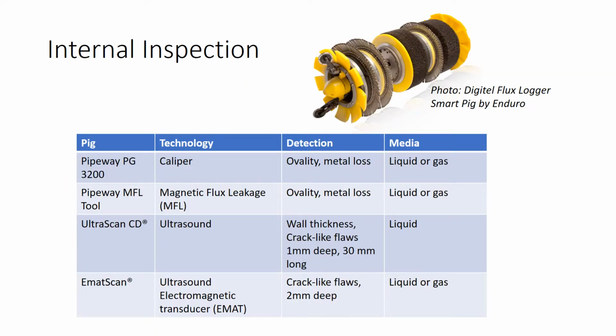We all know pigs can't fly, but can they swim? Well, a pipeline pig is a device that runs inside the pipeline without halting operation. It is generally pushed along with the flow of the fluid. Some pigs are sent through for the purpose of cleaning and picking up debris, while others are equipped with sensors and loggers. The latter are called smart pigs and allow the surveying of vast distances of pipeline.